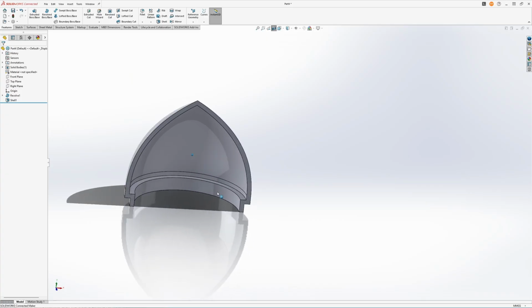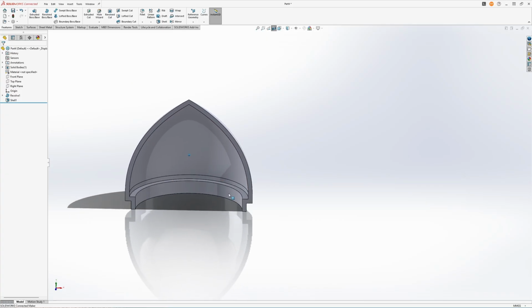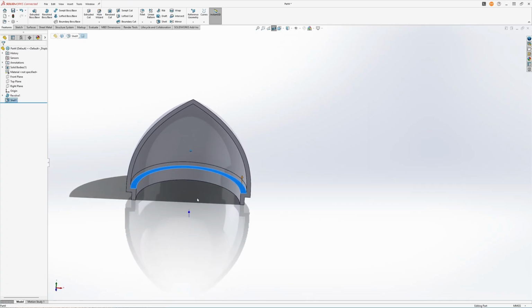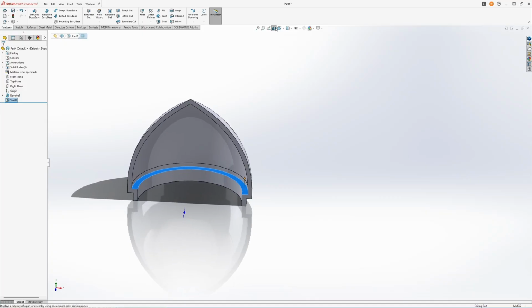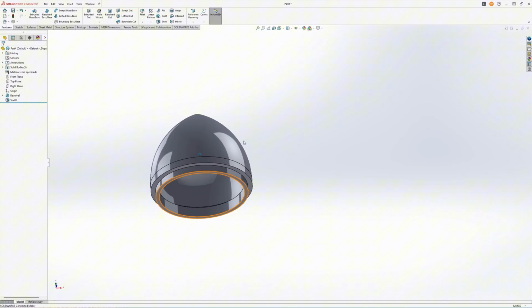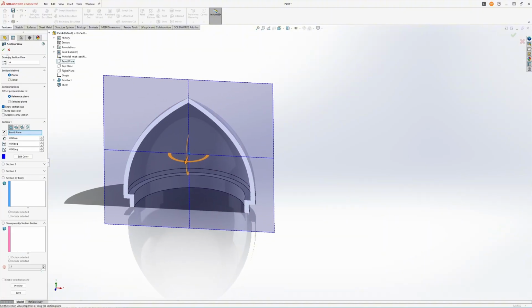Now this would be fairly difficult to machine. Let's say we want to have it machined CNC. We have a step inside the part, which is not easy to remove. As you can see here, if you were to move it, how do you get in there? So one way to kind of fill out the part, which is useful for you later as well, we'll just